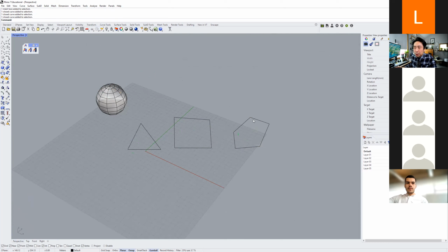Most meshes don't like anything that has more than 5 edges. When you have polygons that have more than 5 edges, it's commonly just called an n-gon. It doesn't matter whether it's 5 edges, 6 edges, 7 edges, 8 edges. To me, it's all the same. It's anything that's more than 4, and they're all bad geometries.